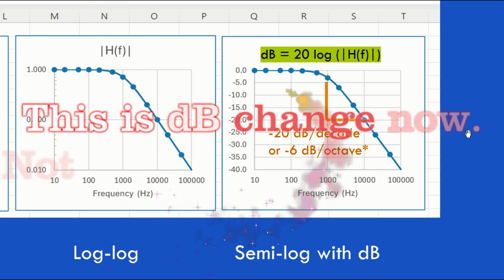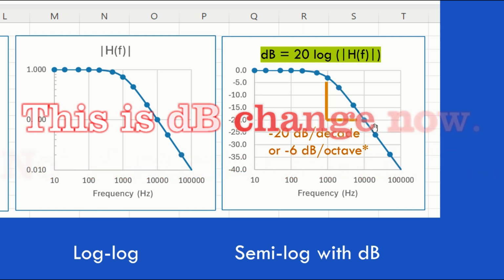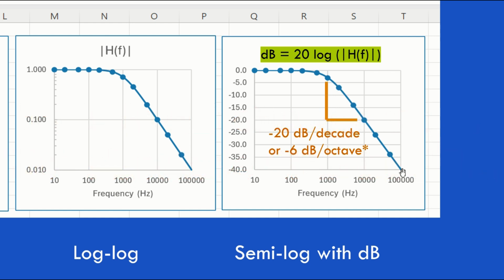One final and very important note from this slide is the slope of this curve. Look, this looks quite linear. Looks like a straight line, that is. And we can figure out what the slope is. Now, if you were to take this straight line and run it all the way up to here, which is the corner frequency, then you could make a plot that has two straight lines, one here and then one here. That's called a Bode plot.